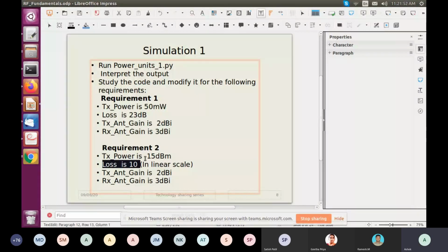So please remember that, especially when you're doing SNR and BER calculations, these precisions, floating point, fixed point are extremely important. Okay, and these could mean a couple of dBs, which is a huge thing in a wireless link budget analysis. So be extremely careful about precision, right? Excellent. I think that was a very good answer, where we understand the importance of precision.